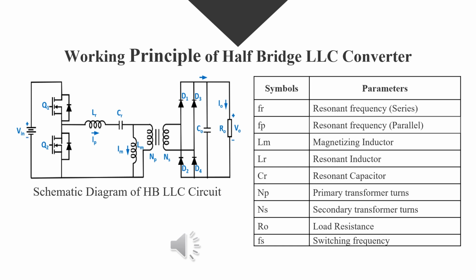Power switches Q1 and Q2, which are usually MOSFETs, are configured to form a square wave generator. This generator produces a unipolar square wave voltage by driving switches Q1 and Q2, which alternate in 50% duty cycles for each switch. A small dead time is needed between the consecutive transitions to prevent the possibility of cross conduction and to allow time for switching to be achieved.